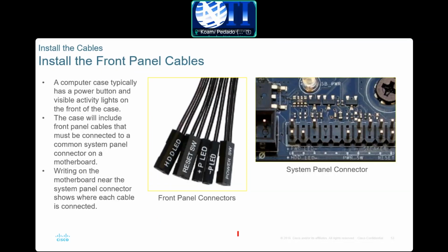But before you put that in, you flip this. If you flip it, you will see there are plus and minus. So you look on the motherboard, which is this one over here. You see plus over here. That means this side is the plus, and this will be minus. So you know how it's going. Otherwise, when you turn it the other way, it will not work. Okay. See, that's how you do it.